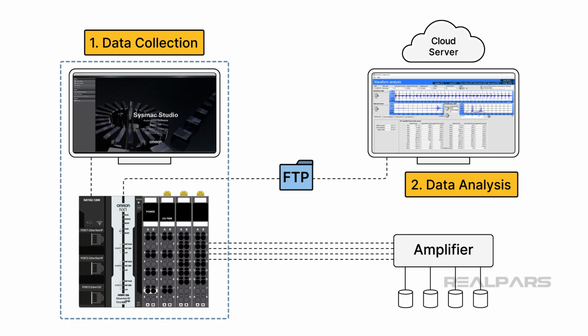Users decide which are the right features that better identify the potential anomalies. The ISO standard ISO 20816-3 2022 defines the norm for the measurement and evaluation of machine vibration. Step 3 is optional, as some customers just want to collect key data to be monitored.